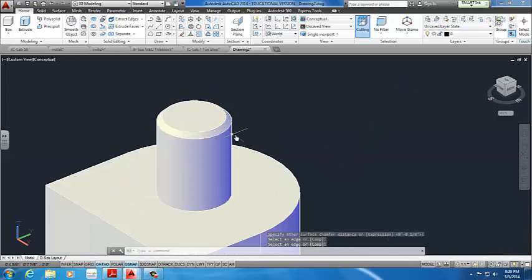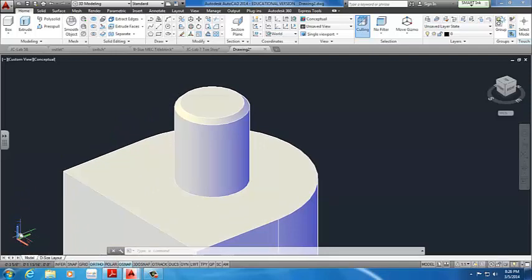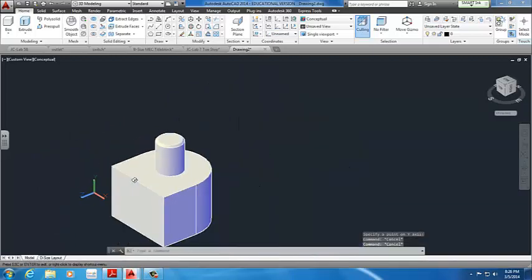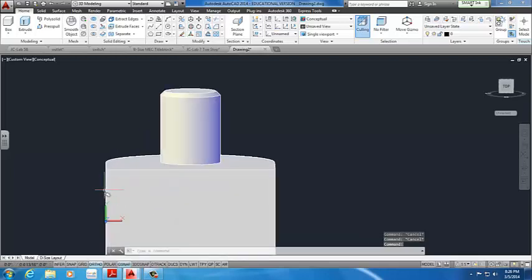Alright, so our next step is actually we have to make a through hole that has a location specified to the end of this face. To do that, we will have to play with the UCS. So what you want to do is, where UCS is, you select it, you take the Y at this point and make it face up, but make sure your ortho is on, otherwise you'll get some weird angles. So you do that. That way it allows you to work on that face, or those X and Y coordinates. If you rotate around, you want to see Z facing you. So Y and X is what you're working with. Z is just facing you, for which you're going to extrude parts.